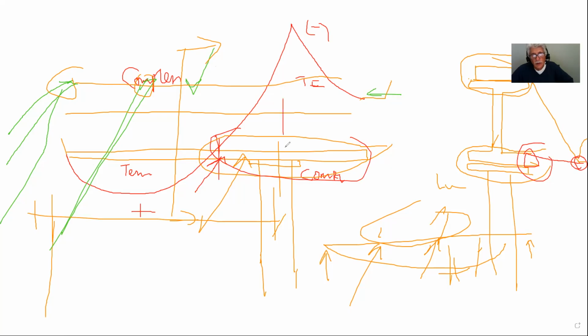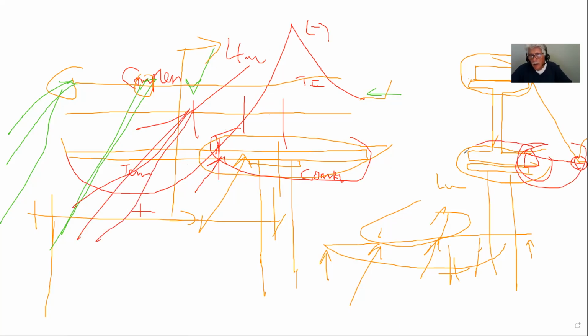And this happens to be, according to ADA, at 4 meters away. If I go back to ADA and look at the point of inflection, the furthest point of inflection is not more than 4 meters away. So if I take my joist here, I can use that joist to create a knee brace to laterally support the bottom flange, and therefore my LU now becomes only 4 meters. And that's why you can reduce the LU.